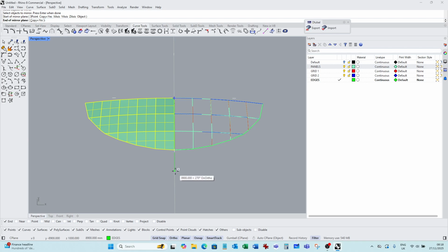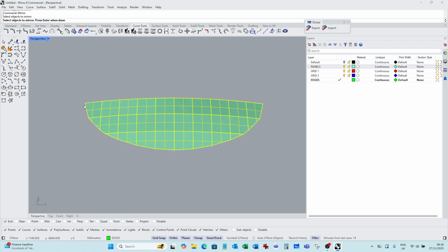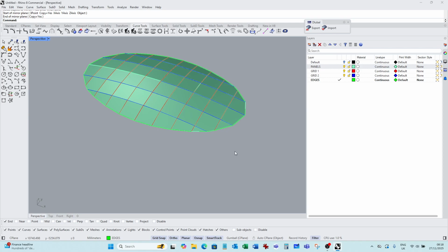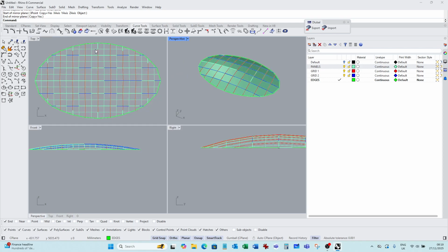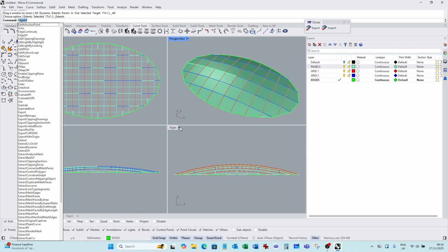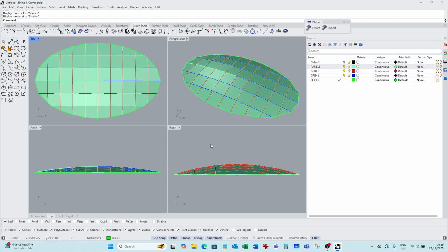I'm going to come down the y-axis and mirror this way first, and we're going to type mirror again, and this time we're going to select all of the items below the line, not the centroid line, otherwise we'll duplicate it, and we can select all the way along the long axis, and now we have the torus construct complete. We can press Ctrl Alt E to see everything in its final glory. If we wish, we can type the shaded views in each of these windows to give us the construct of a torus. And that's the end of this video.